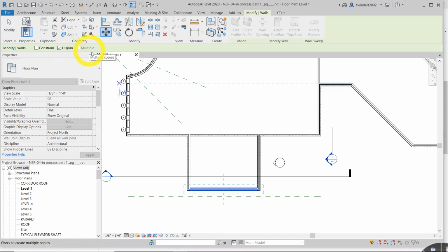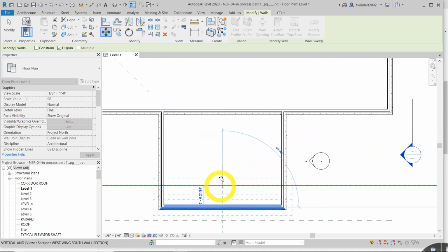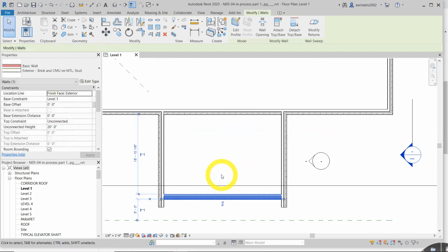So we're going to pick a point somewhere in the middle of the wall, as shown on figure 4.2 on page 174, and we're just going to see our highlight midpoint snap. Okay, left click, and we're going to go in the vertical direction, and we'll type 2 spacebar 6, which represents 2 feet 6 inches, as we're getting to know. Hit enter, and you can see it did not continue to stay joined where they were.